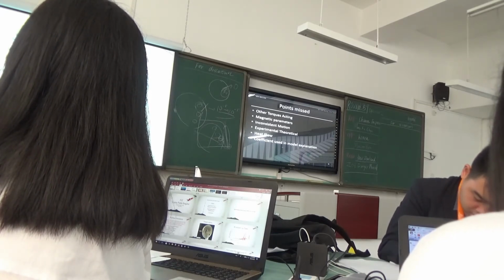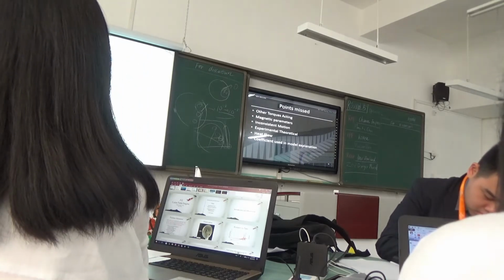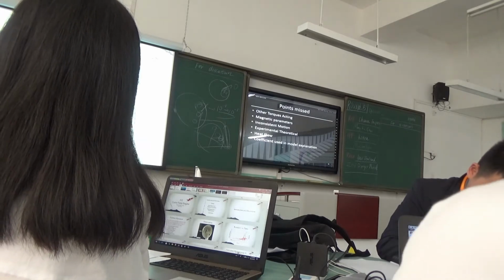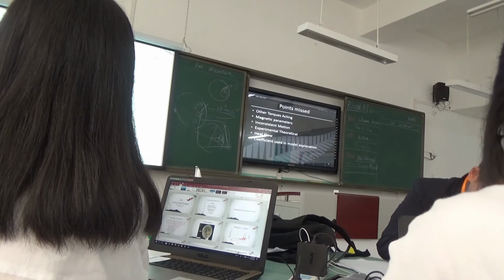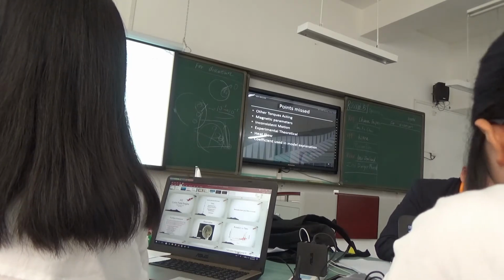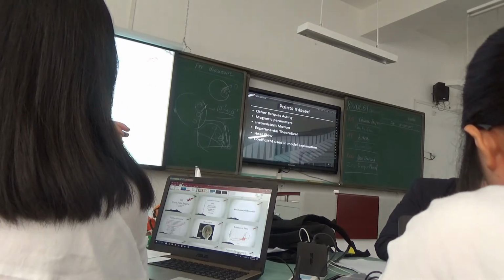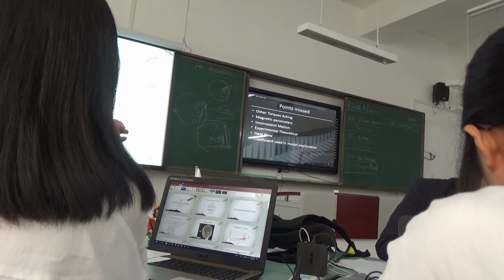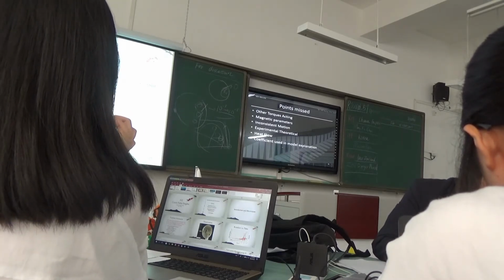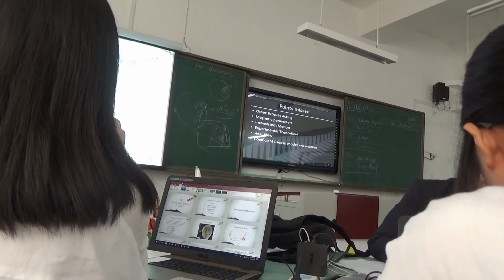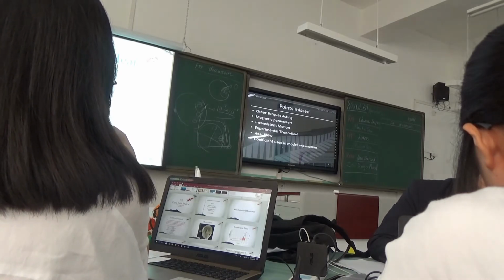That is why we actually observed the most parts of our rotation would be under or just slightly over the Curie point. And as the opponent suggested, there would be a huge drop in the magnetization when it's just approaching the Curie point. We can see here, when it's not actually over, but it is near the Curie point, our actual rotation is actually smoother because there's a bigger magnetization difference so it will cause a better torque to let it rotate. And then also the reviewer asked about, is our magnet constant under the heat?